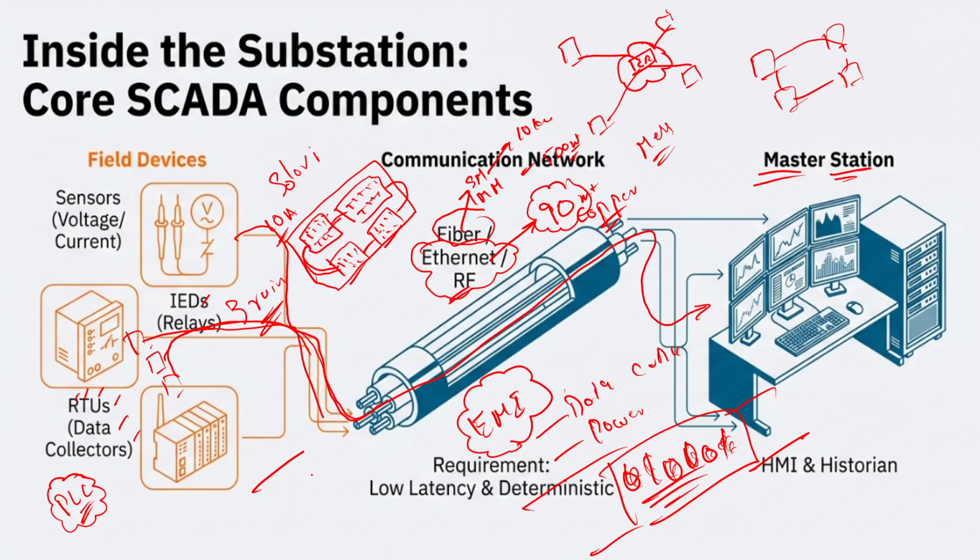The data cable should be in one lane, and the power cable should be in another lane, or else in another trench. This is often the standard, and if you go anywhere, they will first ask about the EMI. If you ask some senior person or some substation person, they always talk about the electromagnetic induction problem, right?